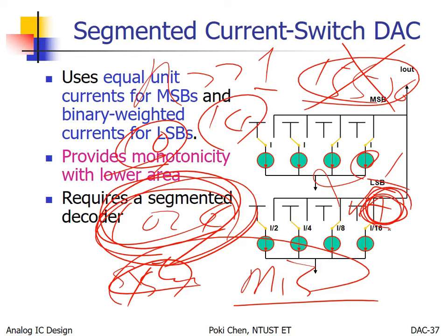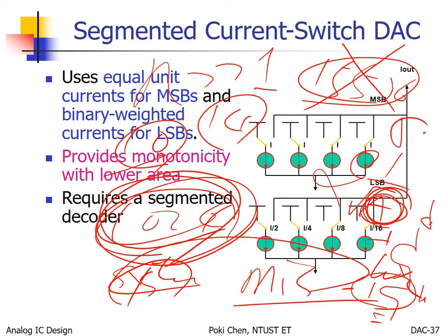Usually, we have a cascode structure to enhance the output resistance. So who controls the current? This one is N-type, and that is the current output. The W by L needs to be large enough. Otherwise, the standard deviation of the output currents will be too much. Got it?